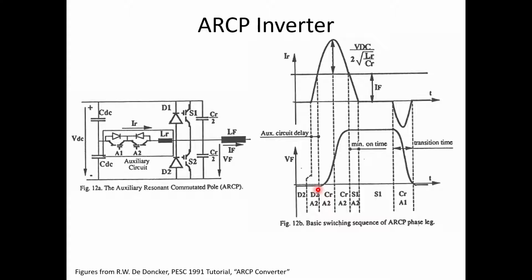Okay? There's all kinds of switching transitions to the circuit. You have to think about what's the load current and everything else to figure out what sequence of steps you go through to get between the bottom switch on and the top switch on, or vice versa.